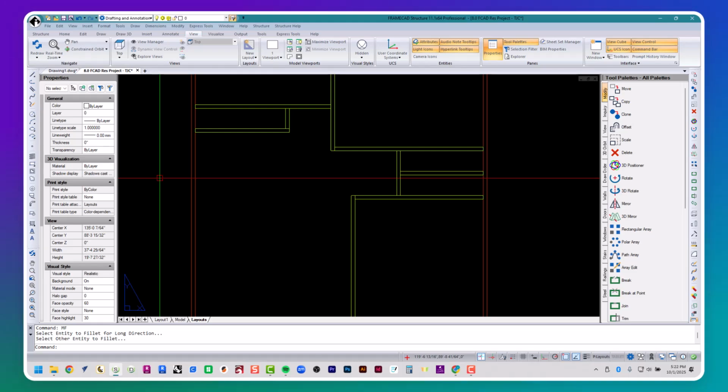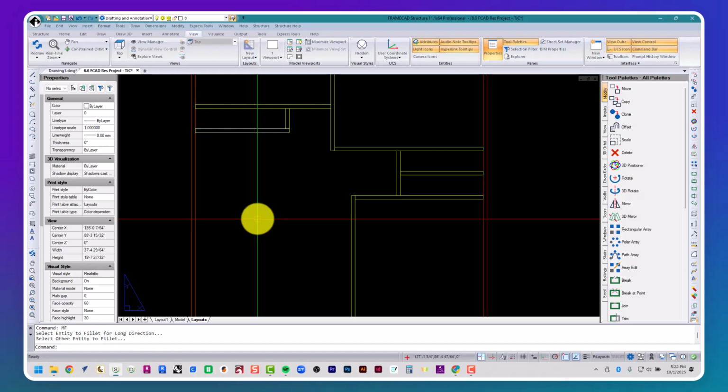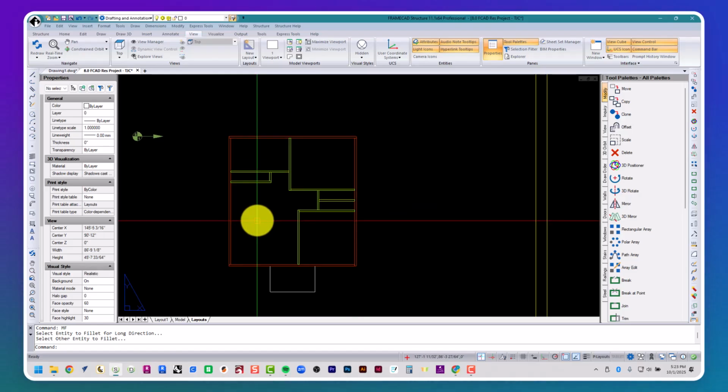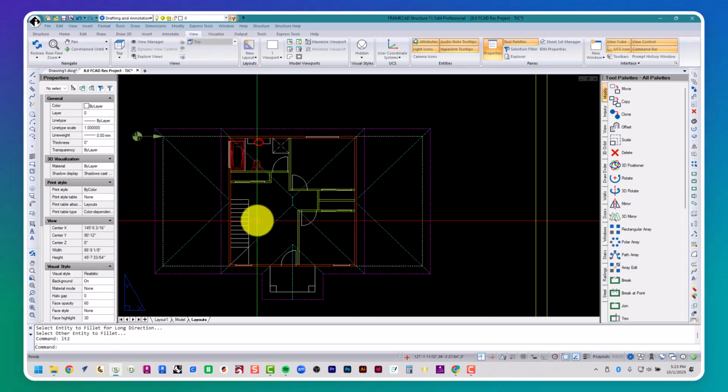User-defined openings. Ensure that the second floor block is visible using LT2. Let's start with the user-defined windows. There's only 4 windows on the second floor. The second floor plan block will have all windows labeled first by its opening height, followed by its opening width. Initiate the user-defined windows command by clicking UW and hitting enter.